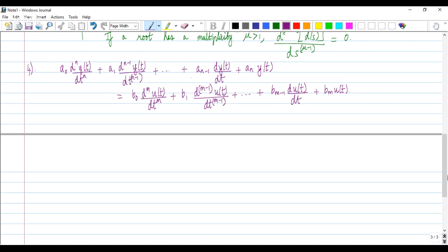Okay, one can show that if I have time varying coefficients, I am going to have different outputs irrespective of the fact that I provide the same input at different instances of time. Okay, so that's how time invariance is reflected in this ODE. And causality is reflected, if you recall, by the fact that n is greater than or equal to m.